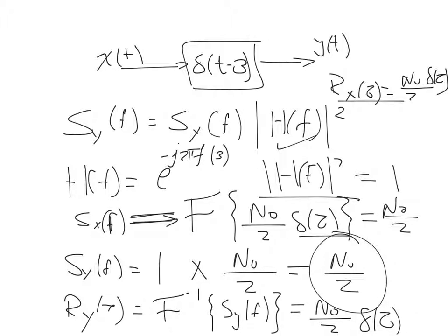You have a random process. You put that random process through a time shift, which is your H of f, right? It's just a time shift. So what happens when you are calculating the autocorrelation of that random process? It does not change. Because starting the autocorrelation at any point is the same, as long as you take the same tau, right? So at the output, you are gonna have the same autocorrelation function as the one that you had at the input. The system is not gonna change the autocorrelation function. Clear? That's how you can explain it physically. But in the end, mathematically you can just get it and that's it. If I ask you a further question, why, explain, then you can say this.